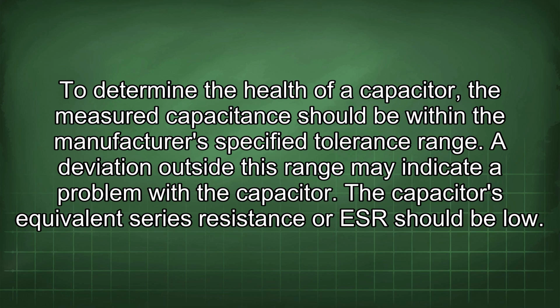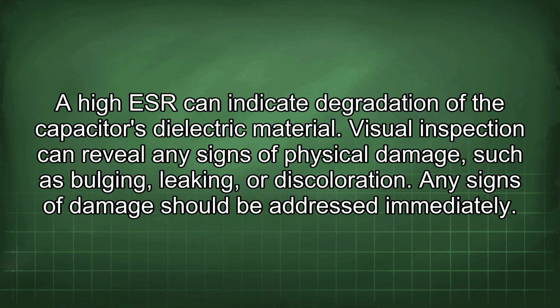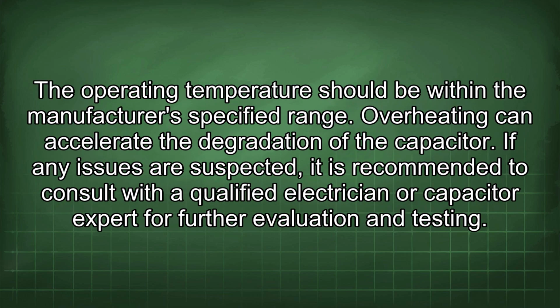The capacitor's equivalent series resistance, or ESR, should be low. A high ESR can indicate degradation of the capacitor's dielectric material. Visual inspection can reveal any signs of physical damage, such as bulging, leaking, or discoloration. Any signs of damage should be addressed immediately. The operating temperature should be within the manufacturer's specified range. Overheating can accelerate the degradation of the capacitor. If any issues are suspected, it is recommended to consult with a qualified electrician or capacitor expert for further evaluation